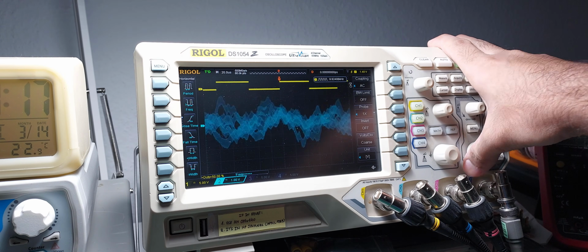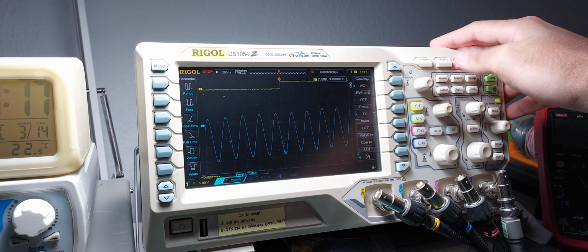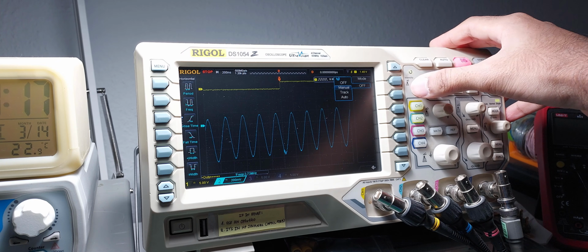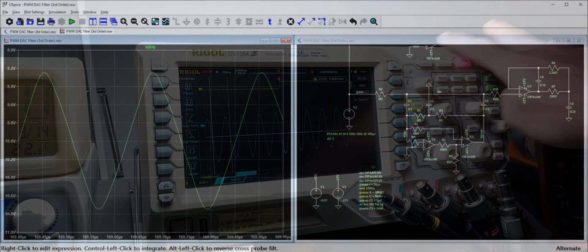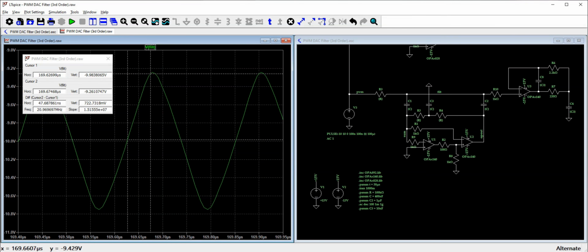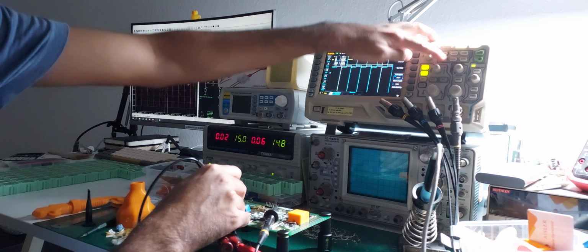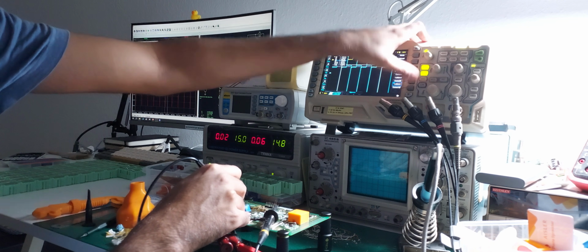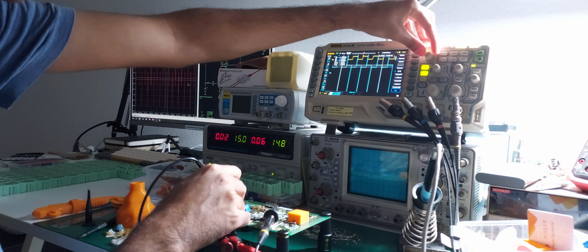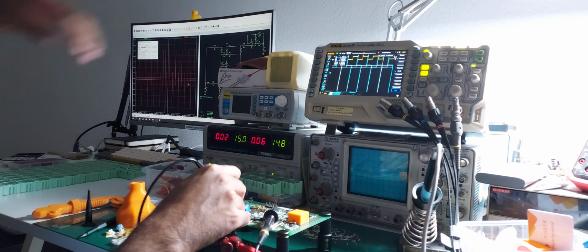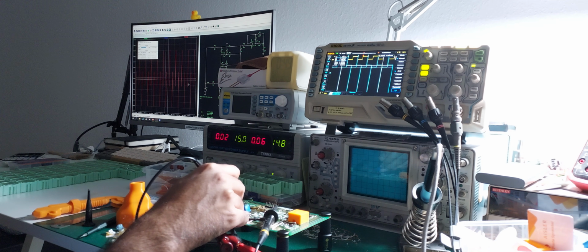An amusing anecdote: at certain compensation values, the composite amplifier oscillates around 4 MHz. LTspice simulates this with perfect correspondence to reality. However, reality decided not to cooperate with the simulation, and the simulated performance gains failed to materialize. I compared the simulation and the circuit node for node, and each node except for the output was exactly the same as in the simulation.